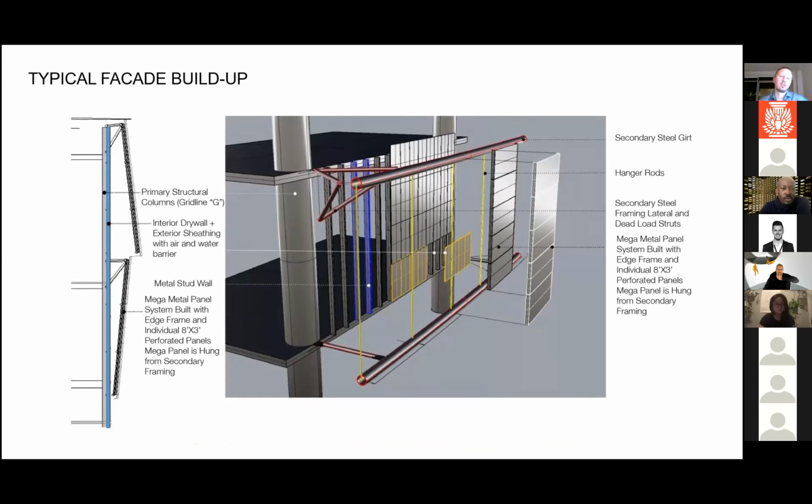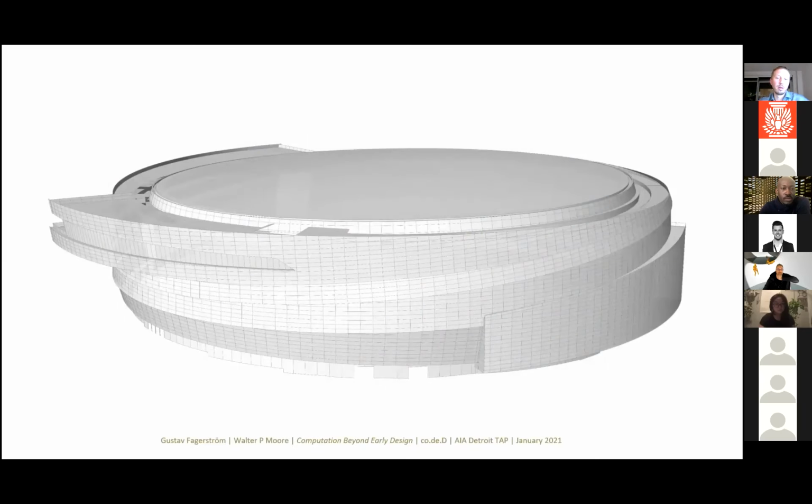Each of these is a planar object, which, when you are analyzing a curved shape like this, if for architectural design intent your panel joints can't always trace the planar lines of the ruled surfaces, then you get curvature in your panels, which you don't want, because then you're going to have to start curving your mullions and your metal sheets and whatnot.